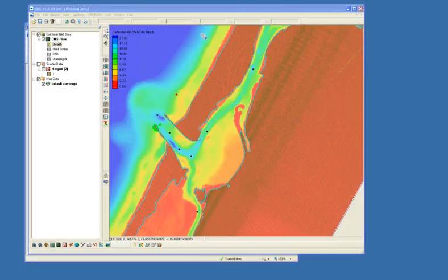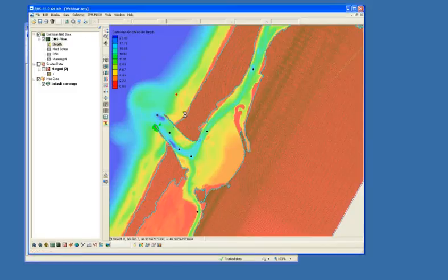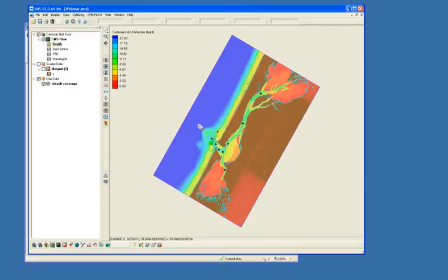So I'm going to go ahead and move on. It's 2 o'clock, and we need to be covering creating telescoping grids. So you see the limitation with this particular type of grid, with the resolution having to go all the way out to the extents of the domain into deeper water and all the way across. This adds a lot of extra cells that really aren't needed. You don't need that extra resolution out here. You don't need the resolution for some of these other places in here.